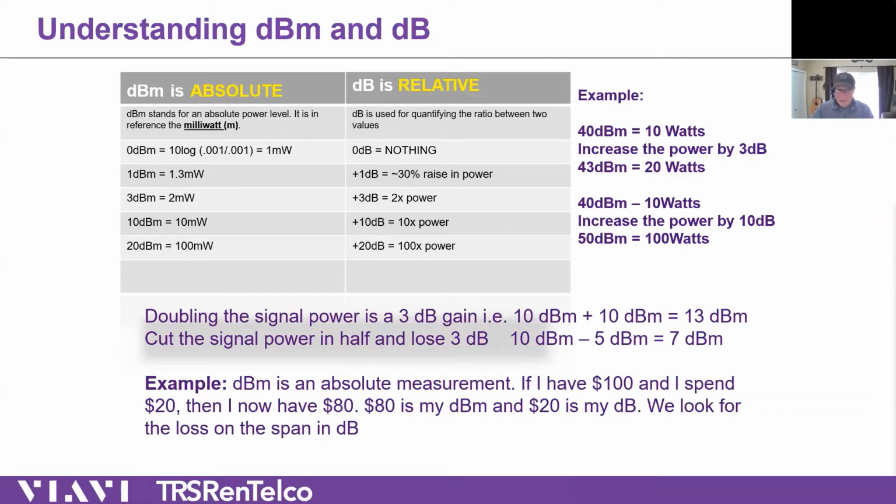Everything you test in your network, if you're using just a power meter and some source, whether it be this SFP as my source, the power meter is going to give me the raw power coming out of this, and that's great. Except it's going to give you the raw power after it goes through your network. So you still have no idea what the power is of this unless you're testing right at this. Or more importantly, if you don't know the output power of this, you read raw power, dBm power, absolute power, you're going to get a number.